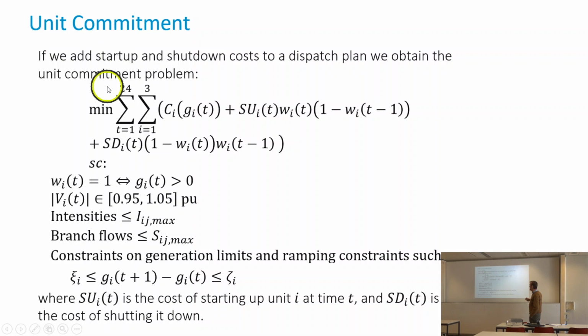We've seen that we typically had to do the kind of optimization we do with DC approximation not just with one single time slot, but multiple time slots. And that led to what are called ramping constraints. This we've seen already. But in addition, typically we also have non-linear elements that are due to startup costs. If I have a generator that is not working at all, and if I want to start it, there is a cost. So the startup cost here is related to a binary variable.